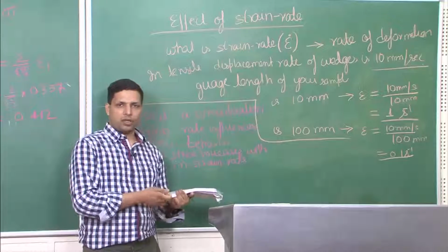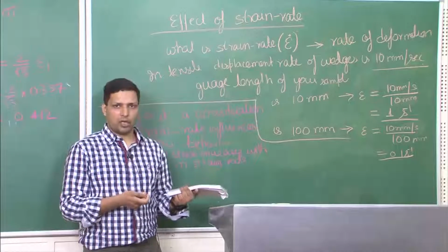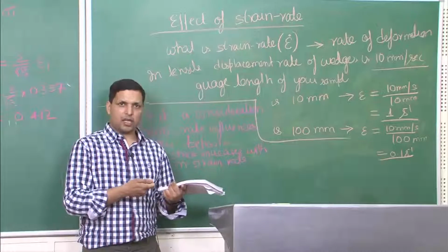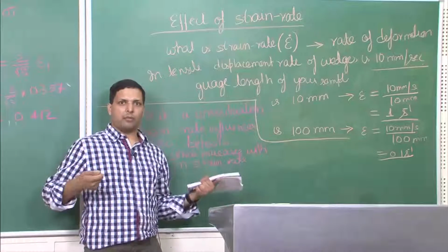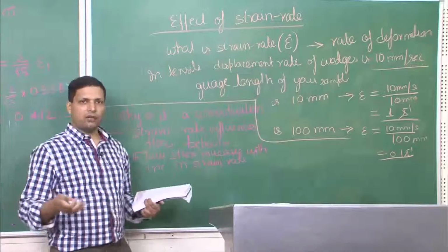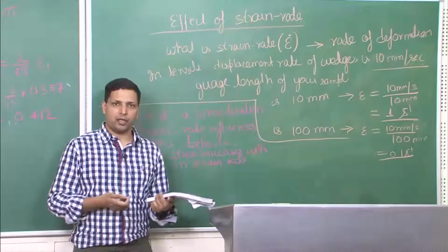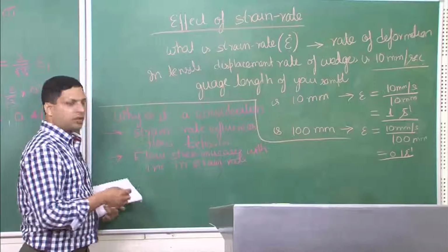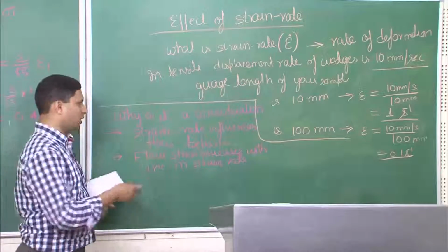In the first one you have done this at a very slow rate, where you will experience that you can deform it very easily. In the second one, try to do it in a snatch, just try to break apart. So you would see that for the same amount of deformation, the second one will require a much higher strength from you, a higher load from you. So that translates to a higher stress requirement.